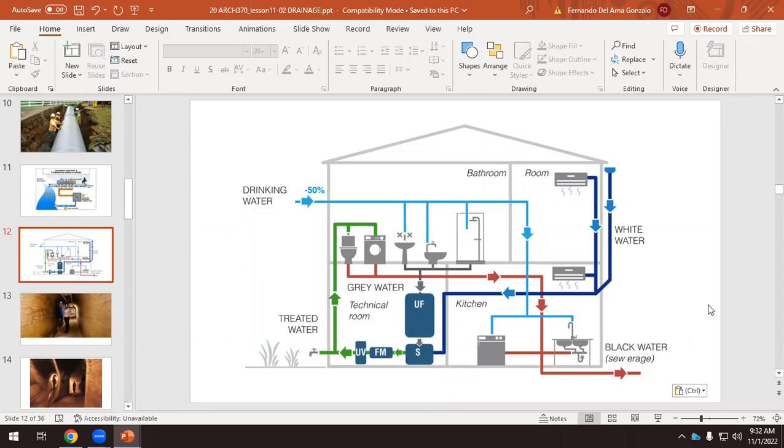So that would be a good building design in terms of water management. There are things that we have to get rid of, which is the black water, but the gray water and the rainwater we can treat in small treatment plants in the mechanical room of a building, and then reuse that water for the plants. That would be the right option for buildings now, especially if we want to get green certificates and LEED Platinum. I'm sure there's some water treatment in this building, because otherwise we wouldn't have the LEED Platinum certificate that we have in this building.